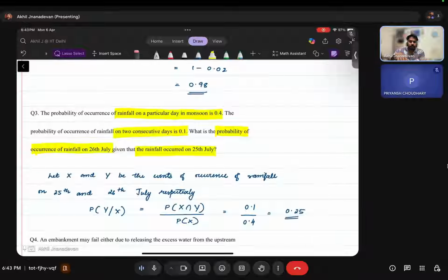We play with these probability values to derive other probabilities, like the occurrence of two consecutive rainfalls. These are derived from secondary processes. The primary process you have to understand is that, like a hydrologist, we need to derive these probabilities, such as the probability that tomorrow is rainfall when today is not. That is something we need to derive from the data, not from the values given in the question. We have to collect the rainfall data for that location from the rain gauge station, convert it into our format, fit the probability distributions, and from that calculate all this.